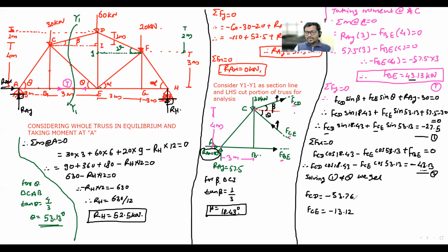Okay, so now the answers for both the forces, that is both the members CD and CE, are negative, which means the assumed direction for both of them is wrong. So firstly change their directions, then we will go for compression or tension. We assumed upward, so correct will be downward. Draw a big arrow like this and tick on it. First I correct CD.